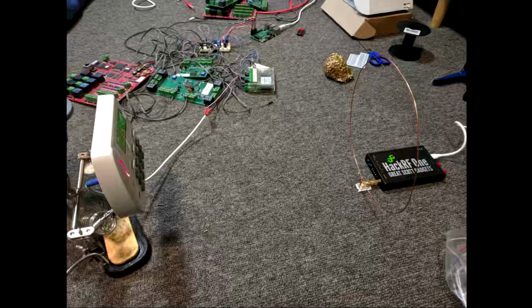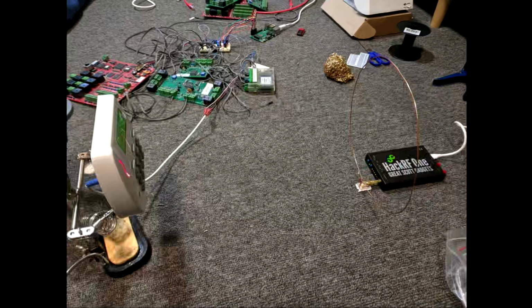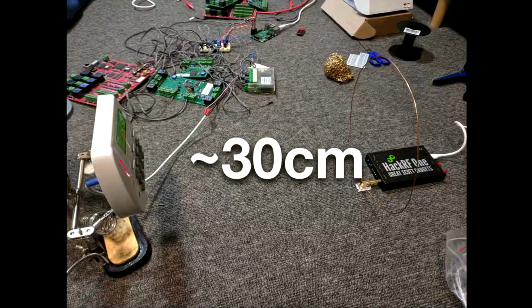So what we can do is take the software-defined radio and put an antenna on it. There's my magnetic loop antenna. Hold it in front of a reader, and basically we can see how far we can see card-reader interactions. This works only about 30 centimeters, so well done, Matt, you did worse. But in this case, physics actually has an answer. Bigger is better for RFID antennas. So with that in mind,